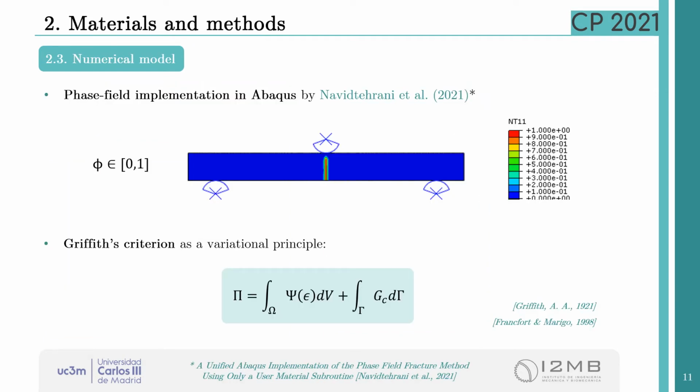For the corresponding numerical model, the main challenge was the modeling of the fracture evolution itself. The crack propagation has been numerically modeled by the so-called phase field fracture model, and in particular we have used a recent code implementation in Abaqus by Navidtehrani.